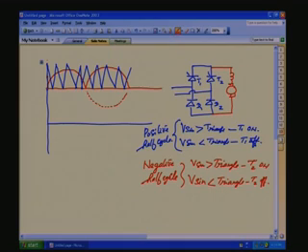So, here the first condition, sine greater than the triangle: from this point up to this point sine is greater than the triangle. So, during this portion this much part is coming across the load. Again, for clarity I will redraw the sine waveform here. Negative we have rectified it. So, rectification happens at the converter side. So, during this portion, whenever sine is greater than the triangle, the top switch is on, and this much portion will be appearing across the load.